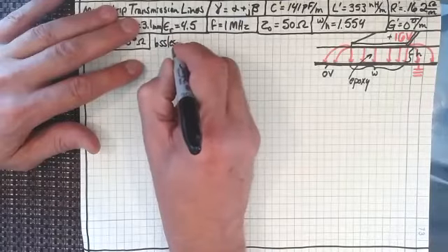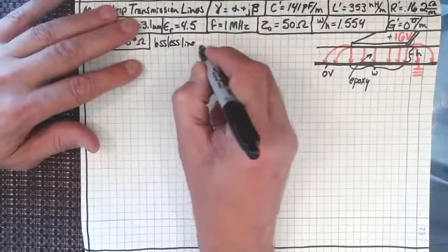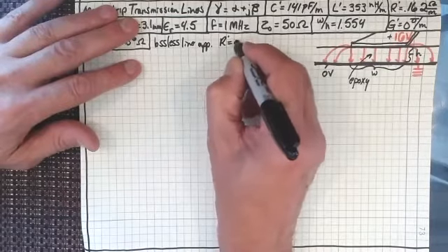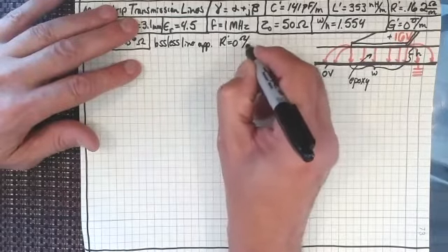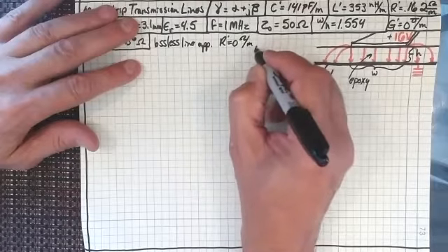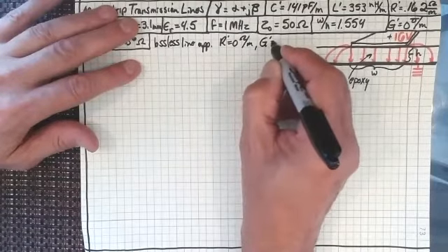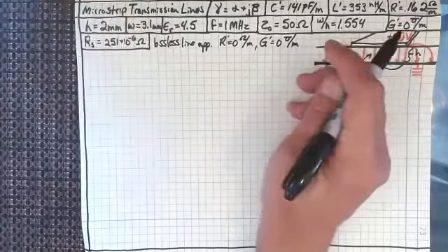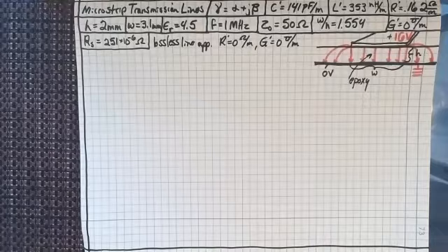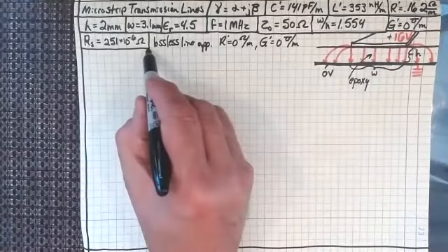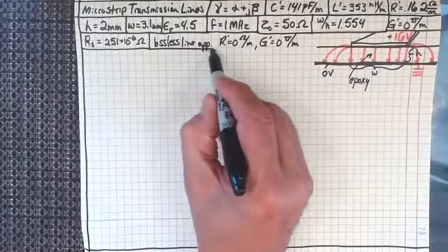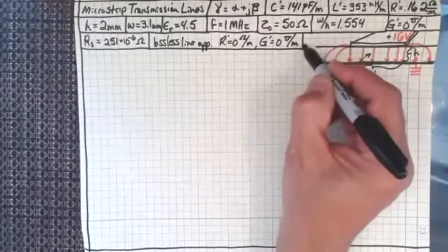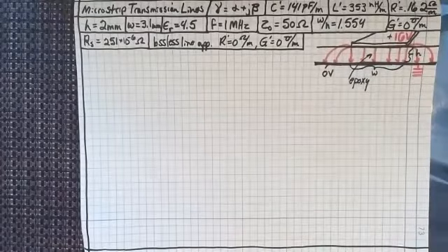The lossless line approximation that I'm referring to is that R prime would be equal to 0 ohms per meter, in addition to G prime being equal to 0 mhos per meter. Yes, I just realized that I have to get back into my lecture mode, which usually meant I had something to drink while I was lecturing.